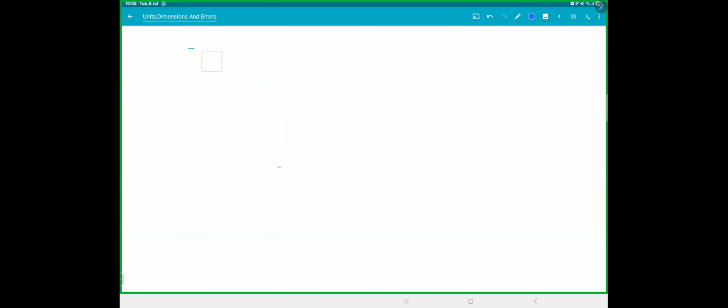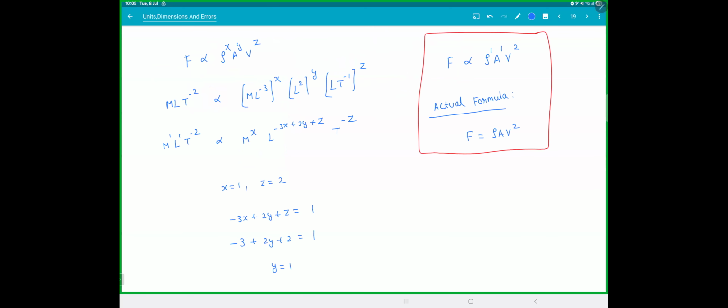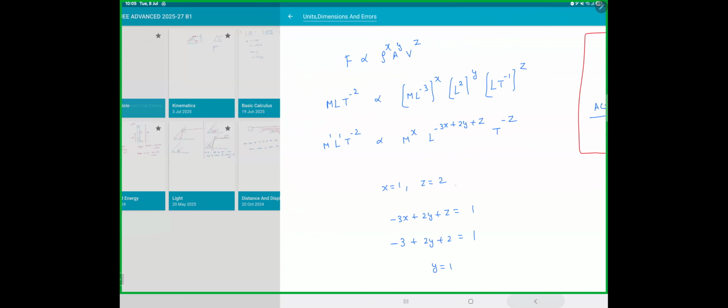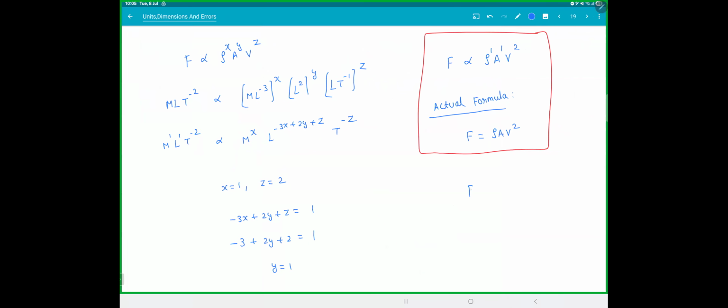Did you guys ever hear about something called water cutting? If you look at this term here, F is equal to rho A v square. We will see this in fluid mechanics. If you divide force by area, this becomes pressure. So let's say the density is 1000, and you're sending water with a speed of 50 meters per second, that will be 50 square, which is 2500. This comes to around 25 into 10 power 5 pascals. That is 25 atmospheric pressures.